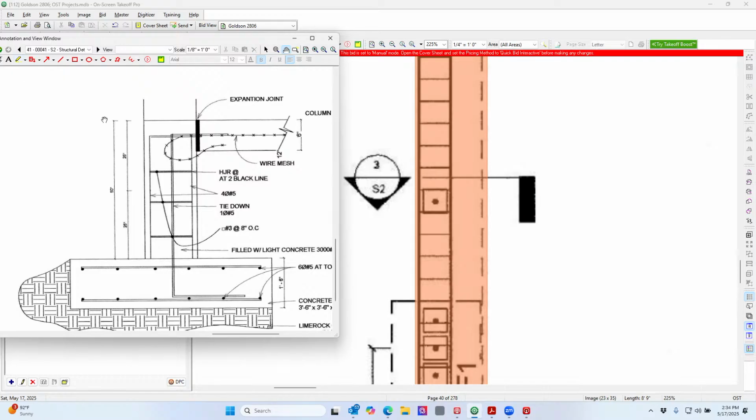Correct. So what I would do is that vapor barrier is going to be here, and the soil poisoning, and then you're going to have dirt fill all up in here. So when you're creating your element for this interior, are you creating the element for the vapor barrier or for the concrete? What I do, I take it all off because it's going to be the same quantity.